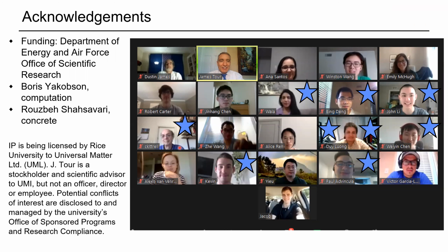True. Just a follow-up question, because this is an area that we're working in, using graphene and other materials for enhancing membrane performance. With the laser-induced graphene technique, can you also control the Z dimension, the depth? How thin can we make this treated layer? Because in a membrane, we need this to be really thin. If you just take your typical laser on polyimide, you get about 20 microns thick.